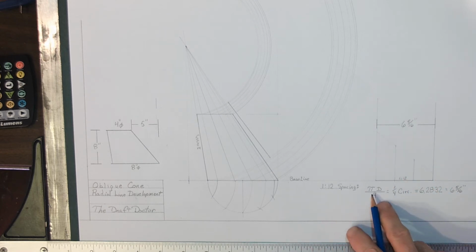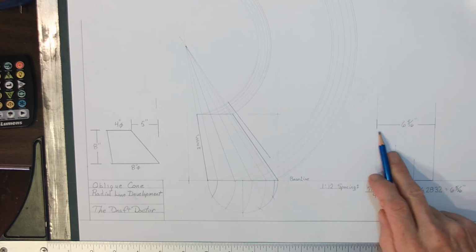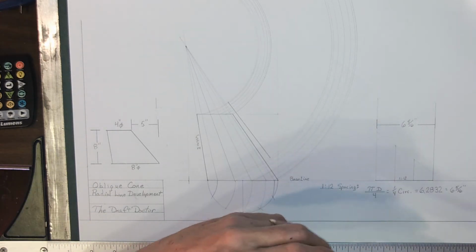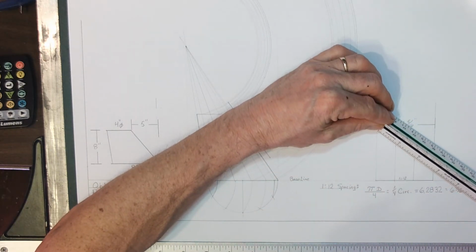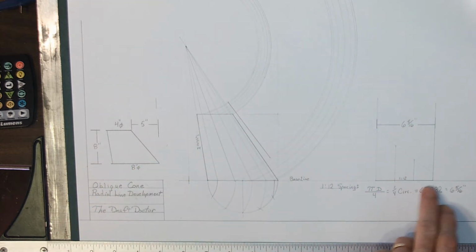Quite simply, I took the diameter, 8-inch round, times pi, divided by 4, and I got 6.2832. Subtract 6, times 16, tells me it's 5/16. So I laid out parallel lines, 6 and 5/16 apart from each other. And then I used a rule, and I lined it up when I had 3 inches or a multiple of 3 on the diagonal. I marked each one. When I plumb it down to my stretch out at the bottom here, I now have my 1/12 spacing. All right.